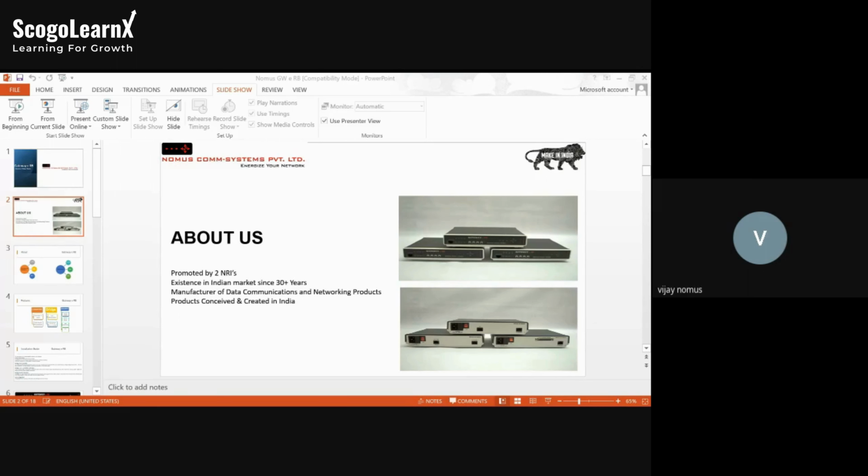In the front panel, you will find 8 LED indications and 4 push buttons for diagnostics and generating a loop towards the WAN interface. Among the diagnostics buttons, only DL1 will work, and only for the WAN interface. We will generate only a loop test through the WAN interface. For the LAN interface, which is the Ethernet side, we cannot provide any loop detection mechanism. We are providing it only for the WAN interface. So DL1 is the only diagnostics button.